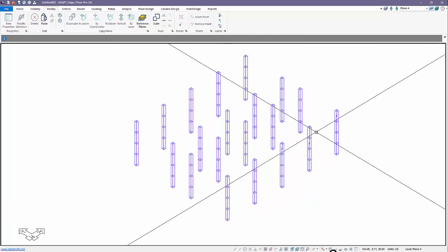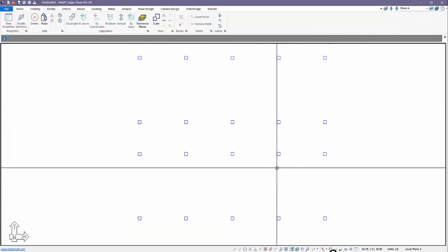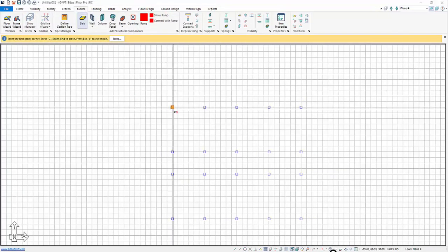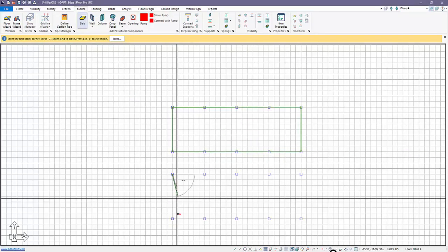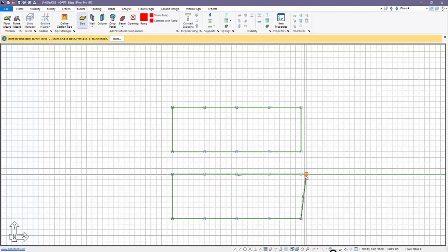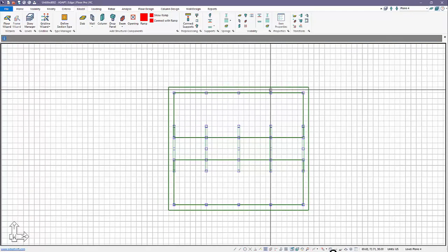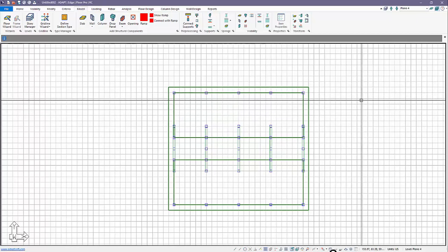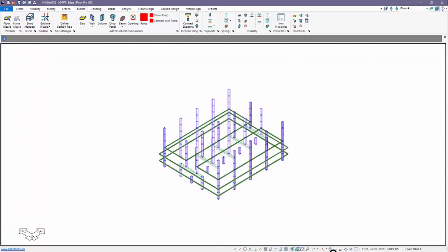And then finally, if I go up to level 4, let me switch back and toggle to level 4. We're going to create 2 slabs. Okay, so we'll model a slab region. So the building basically splits at the level 4 and above. There's slab region 1 and slab region 2. And you'll notice this is a 30, let's see, 10, 20, 30 foot span there. So that's fine.